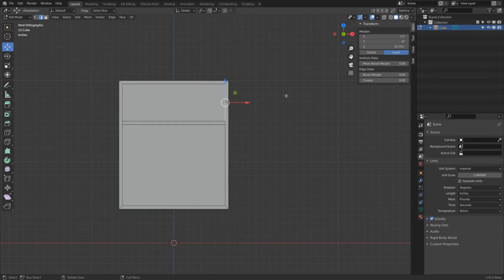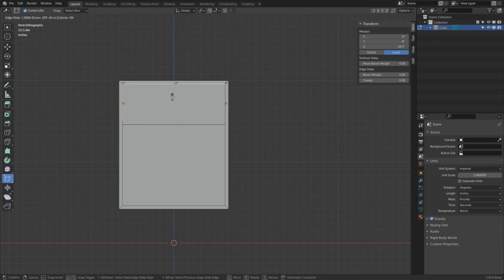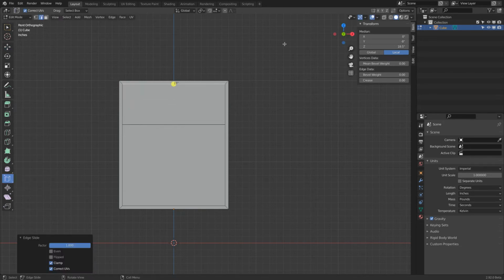If we want to be more precise, because this was more eyeball based on the rounding of the numeric values, we can also do the following. So I select this edge, and here is my edge slide, and I slide to the top. Very good. Just make sure, however, because in some videos I show how to auto merge vertices, we do not want this to be turned on.